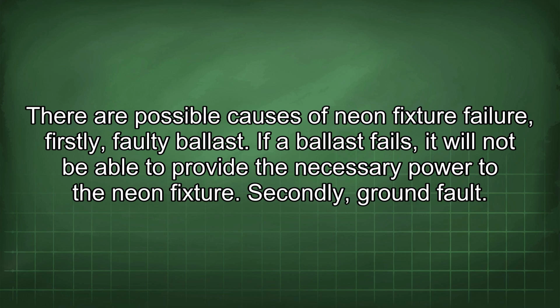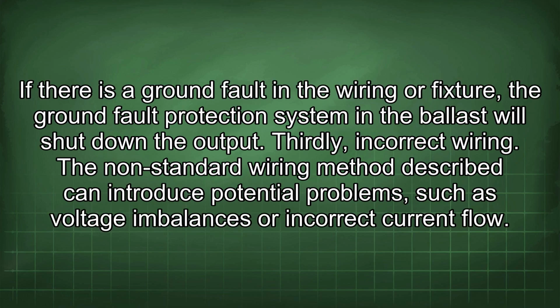Firstly, faulty ballast. If a ballast fails, it will not be able to provide the necessary power to the neon fixture. Secondly, ground fault. If there is a ground fault in the wiring or fixture, the ground fault protection system in the ballast will shut down the output.